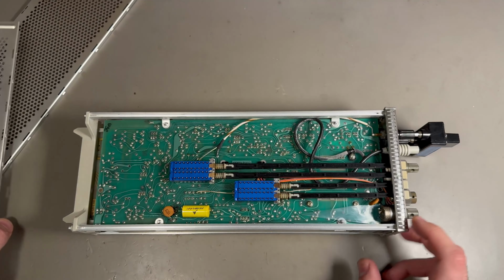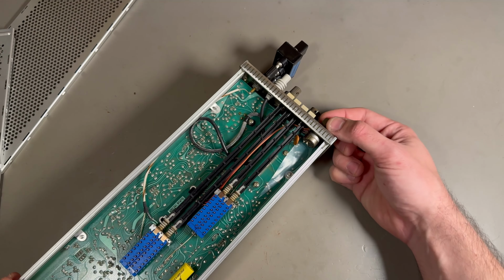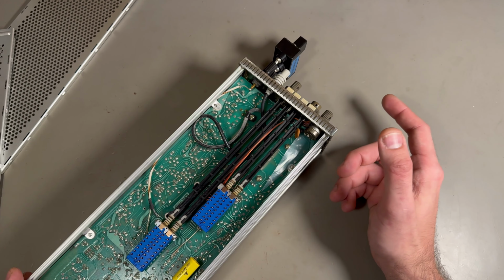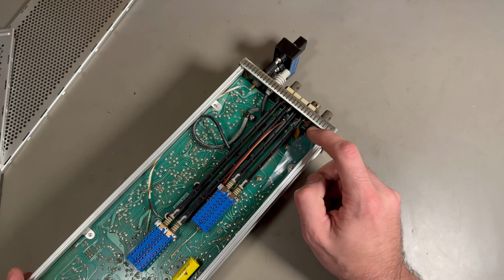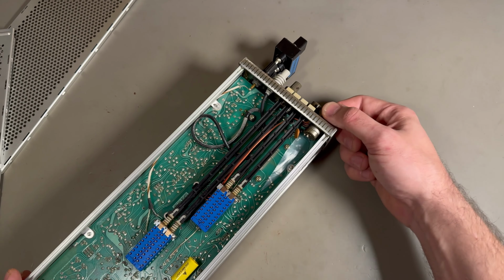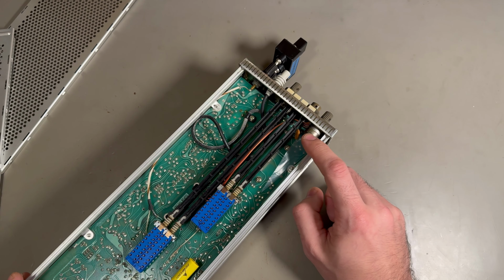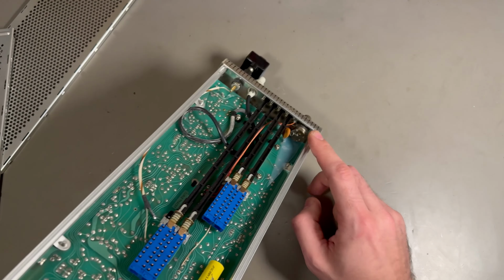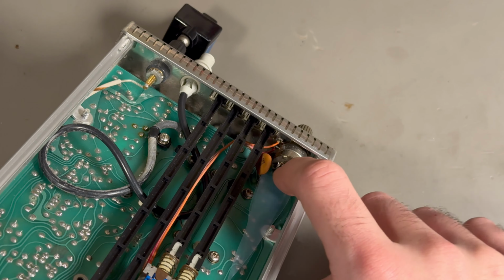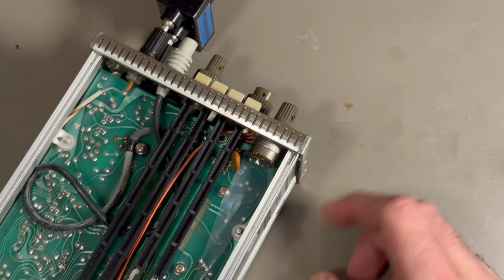Oh, by the way, this is a repair I made. This collector volt potentiometer is the most used one on the device. It was very worn out. It was basically falling apart, and I couldn't find a perfect replacement. This one has a switch on it that isn't used, and it was too long, so it's shorting out something on the board. So I just stuck a piece of dielectric tape in between them. So I'm still waiting for a proper replacement for this one.